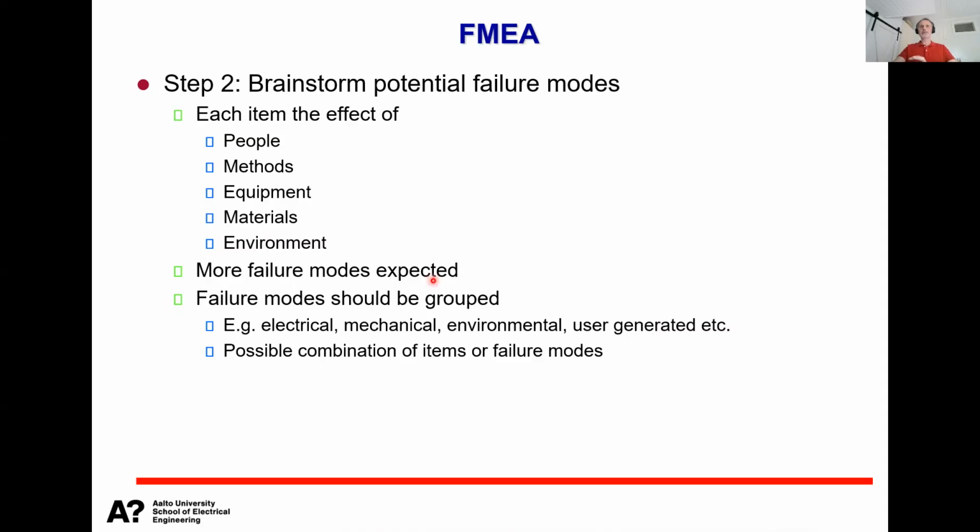So you group them according to different categories so that you can have a combination of failure modes, because quite often with a single improvement you can affect several different failure modes or mechanisms. So meaning that with one hit you can get more flies. So your corrective action has more effect if it affects several different potential failures rather than only solving the problems one by one.